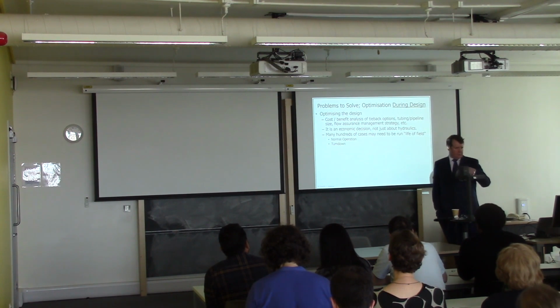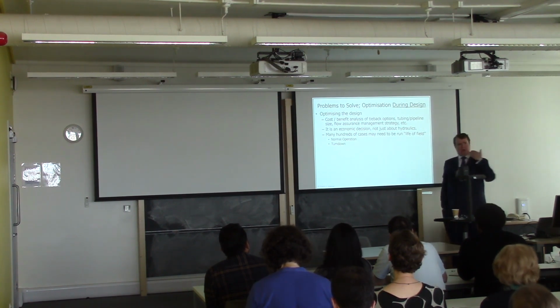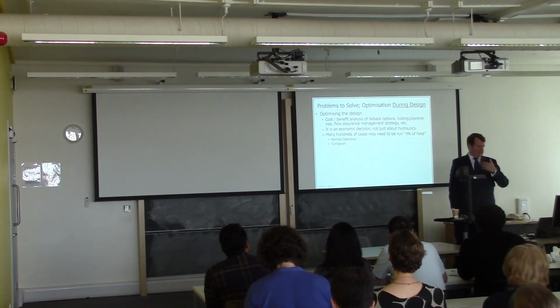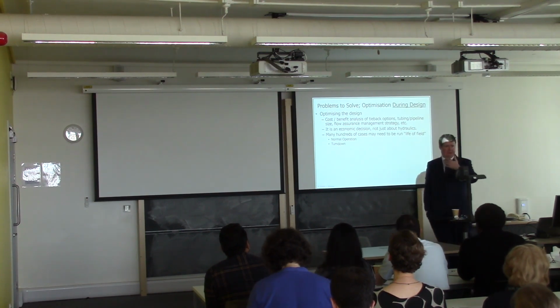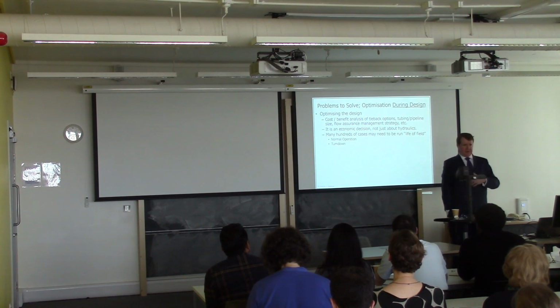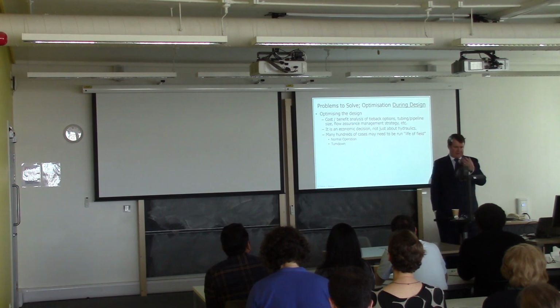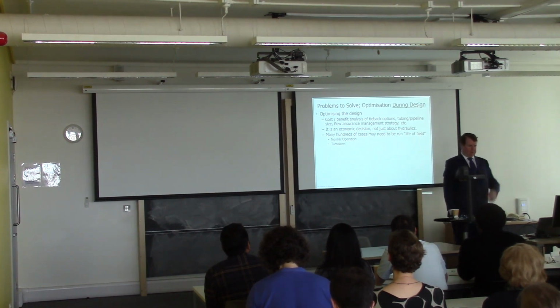And we don't just want to optimise it for day one or the first year of production. We need to optimise it for the whole life of the system. And the system will change as the reservoir depletes, drops in pressure, changes composition as it's generated throughout life. So many life of field simulations need to be run to see where you're operating this model, the way it would be operated in reality, normal operation.